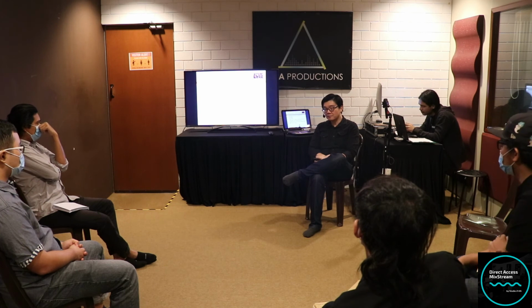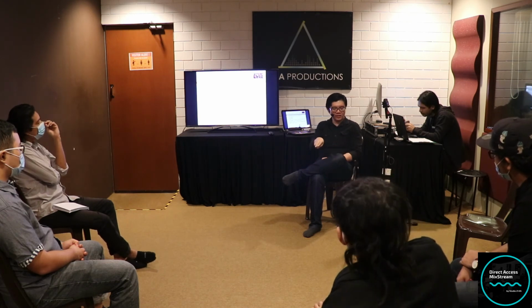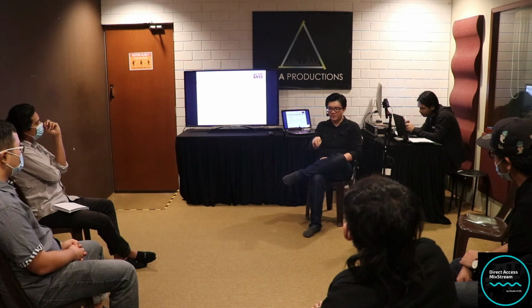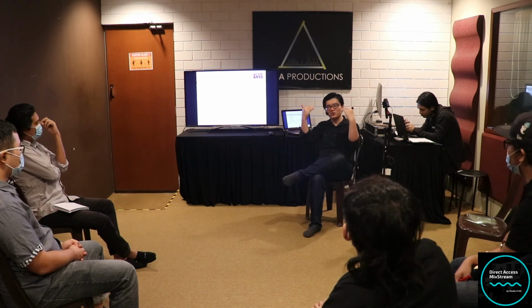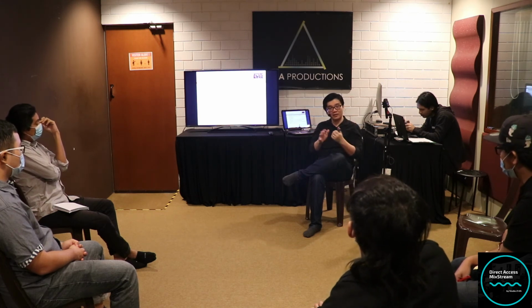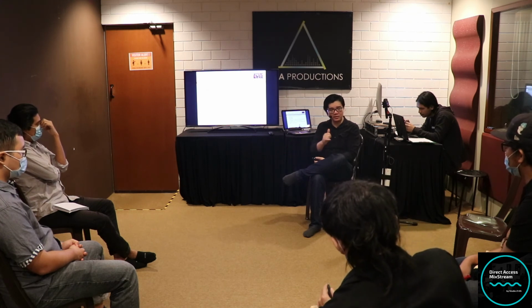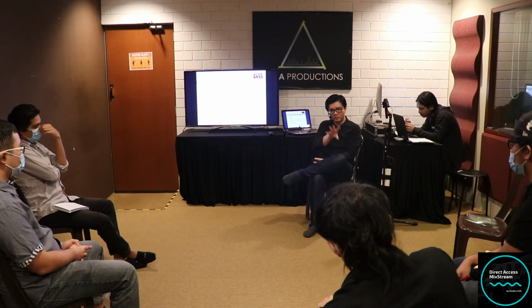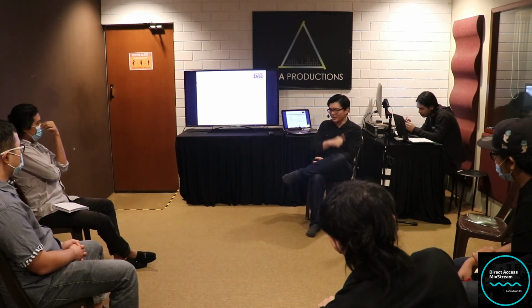So in mixing, either inside the computer or mixing for an audience, when we talk about effects, if we bring down the volume of the vocal, for example, we want the reverb to come down accordingly, by the same amount. That's why you route something pre or post. So in this case, we route it post. So you guys are clear? You understand where the application of pre or post is? Okay, we cool? Okay, let's move on then.